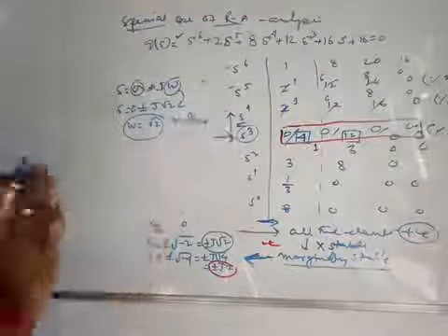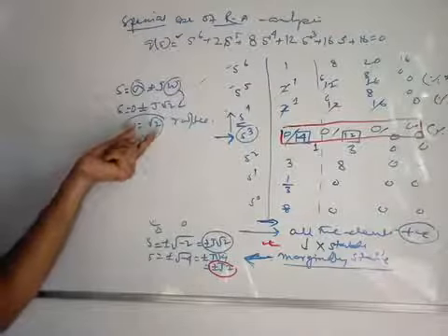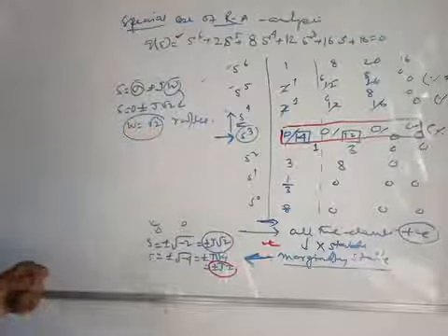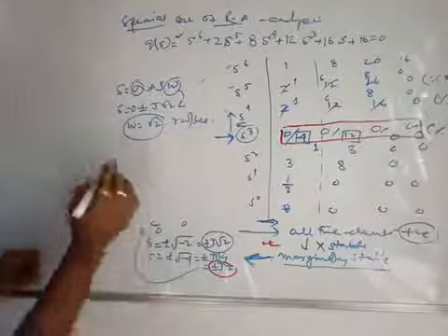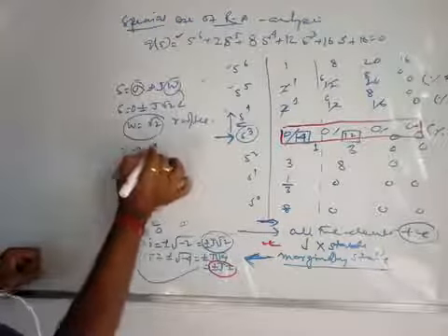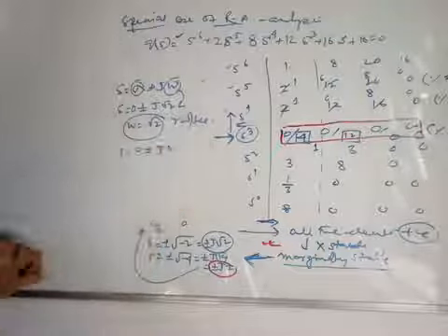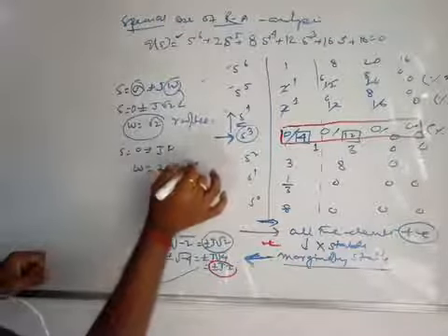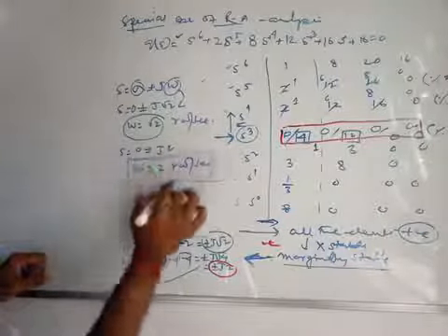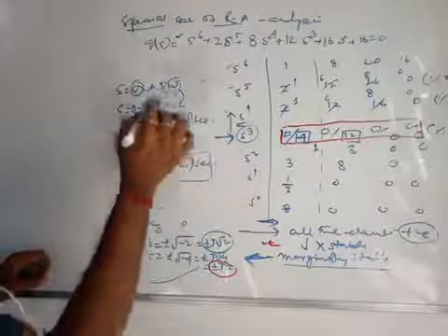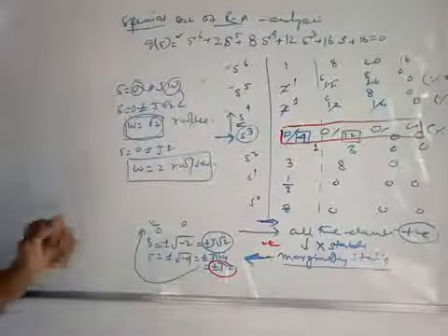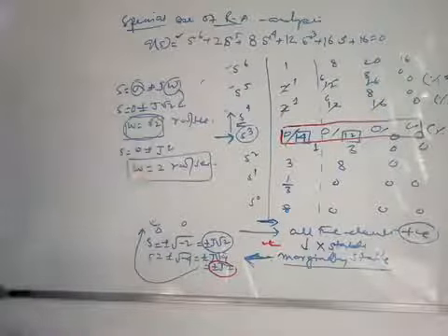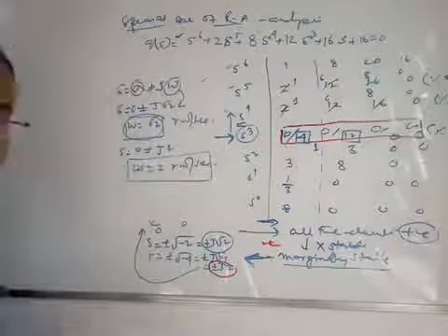That means the system may oscillate with the frequency omega equal to root 2 radian per second, and from this part again s is equal to 0 plus minus j 2. That means the frequency may be 2 radian per second. So this system we are dealing with may have two frequencies. One is root 2 radian per second or 2 radian per second, right?